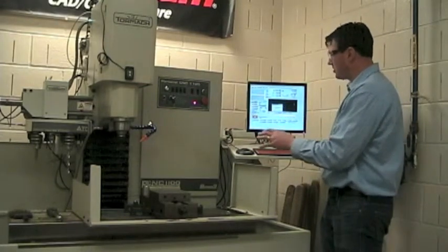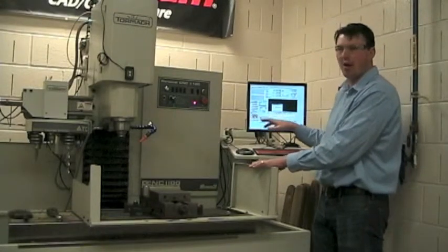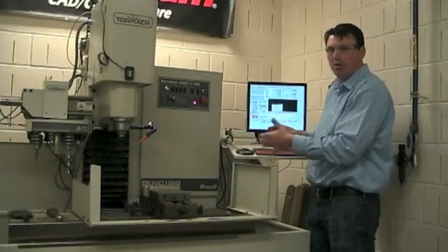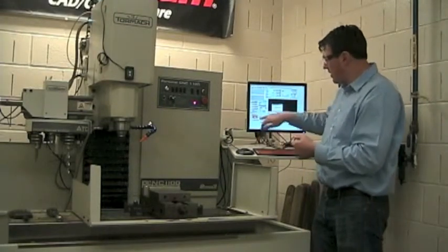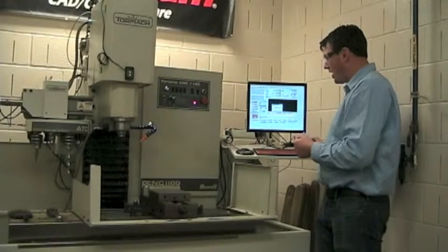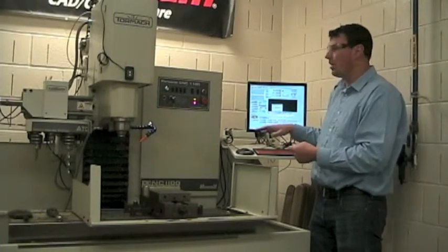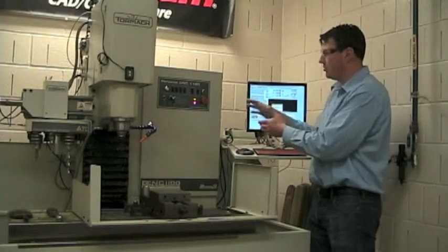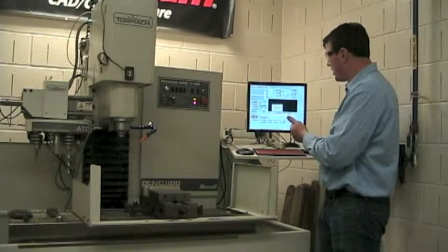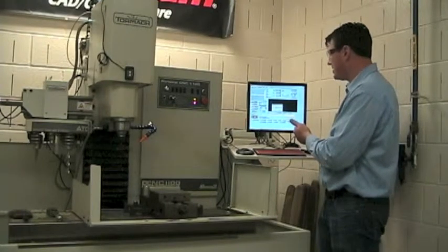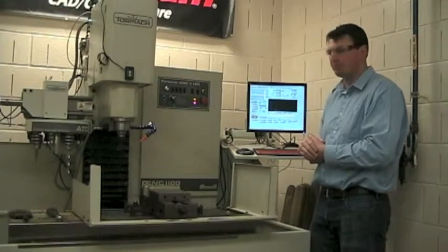Now I'm still not connected between machine and controller. What I need to do is come to the lower left corner of my screen. There's a flashing red bar. Typically on this controller, red lights are a bad thing. We want lights to be green. This is flashing red. When I click reset, it will say machine OK. I now have established connection between the two, and you'll notice that computer is lit up. Now when I click OK on this ATC warning menu, it should recognize the ATC controller.